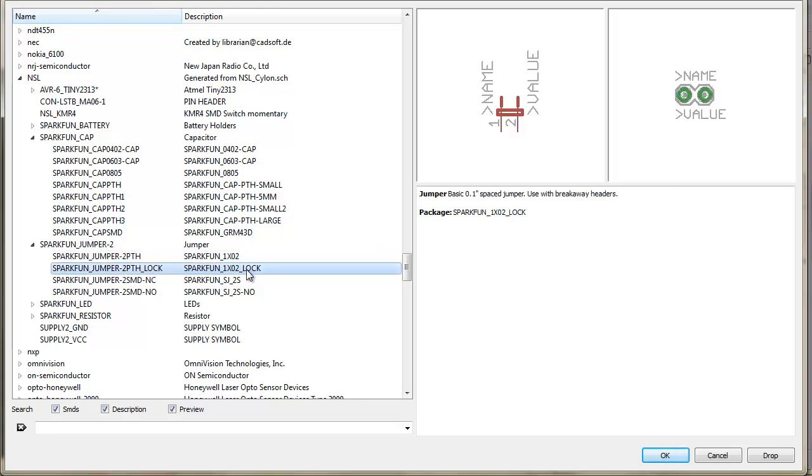Now, one thing SparkFun does is kind of interesting. They have the lock. So this would be the normal one with correct pin spacing. What they do is you can look at the top here, they'll change. You basically just move it out ever so slightly, and that helps them when they're creating their products by hand. So it offsets the spacing a little bit, and so when you put the through-hole component in there, it'll stay in there because it's being held in the holes, whereas this one normally wouldn't, and it'd fall out. So they use that as part of their manufacturing process.